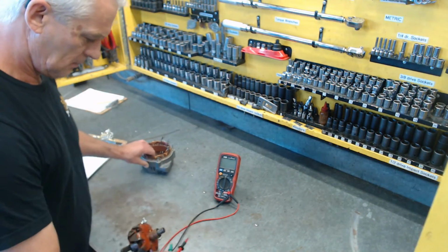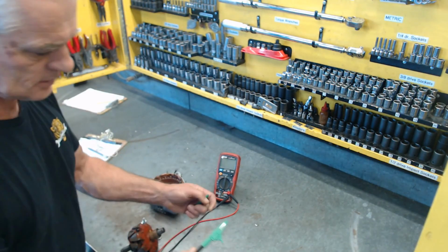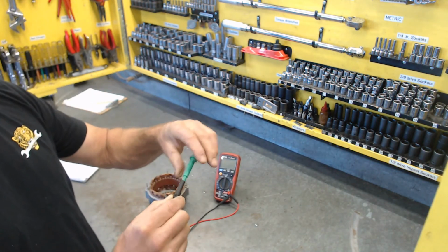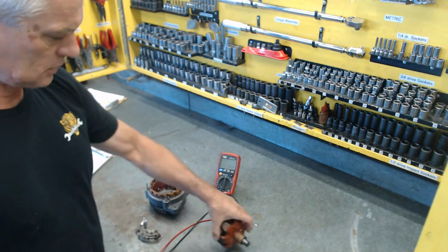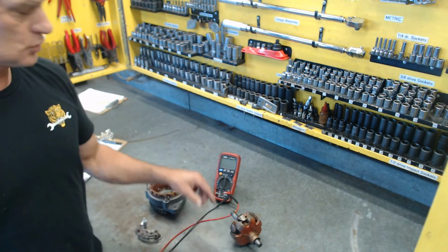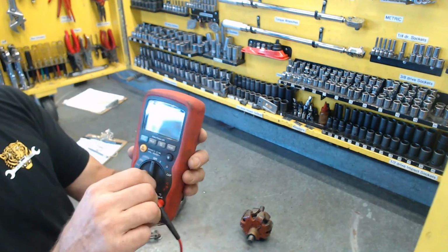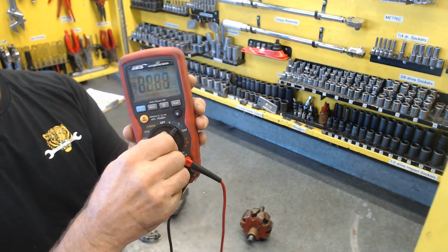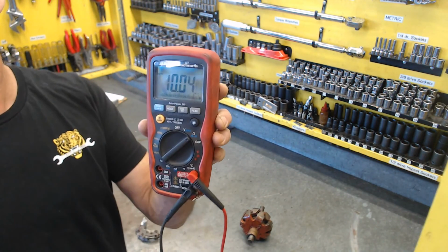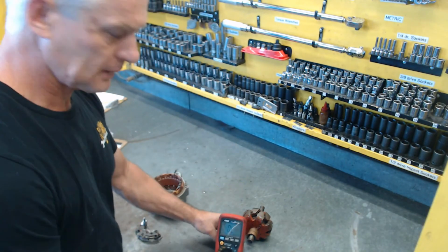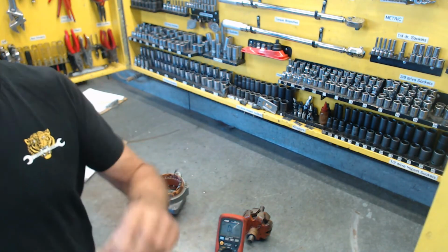I'm going to take my leads, my banana connector. I'm going to take off that alligator clip. I'm going to put on a probe like this. First thing I'm going to do is look at this rotor for shorts to ground and opens, and resistance. I'm going to put the meter to ohms, so you can see the Greek omega symbol and auto zeros. And I can put this down. It's going to read OL because that means out of limits.